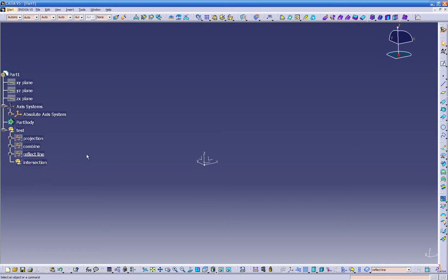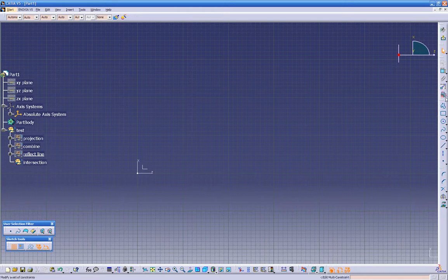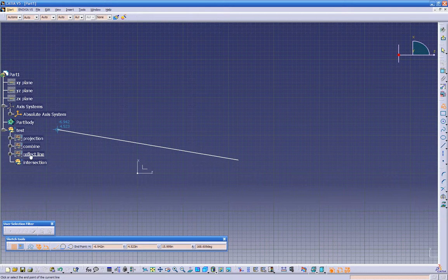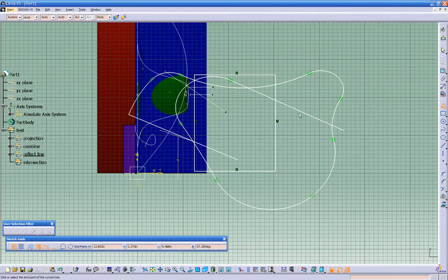Let's make this the default, because right now if we try to build a sketch, for example, and we try to make a rectangle, we don't see it, right? We try to create a profile and we can't see it. It's like, what's going on? The reason we can't see it is because this is the default and it's already turned off. So right now everything that we're building goes onto this folder, the no show level. So if I go to swap visible space, there we go. This is all what I'm creating right now. Because this is turned off, everything that I'm working on goes into this level.